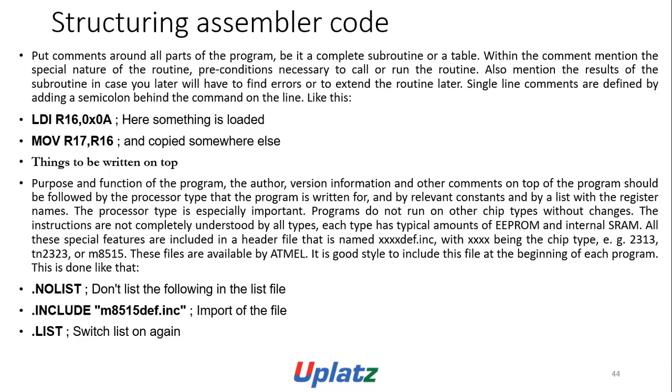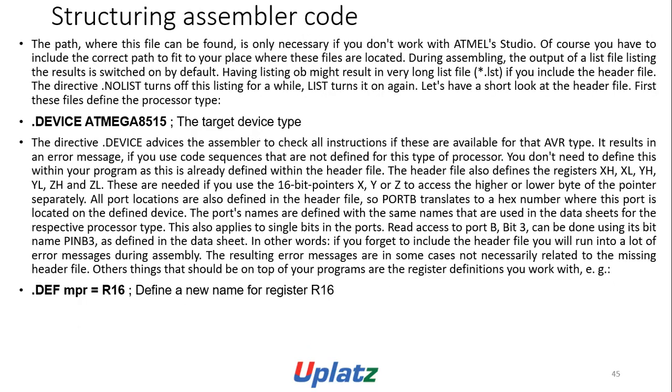This is done like that: .nolist, don't list the following, .include m8515def.inc, import of the file, .list, switch list on again. The path where this file can be found is only necessary if you don't work with AVR Studio. Of course, you have to include the correct path to fit the place where these files are located.